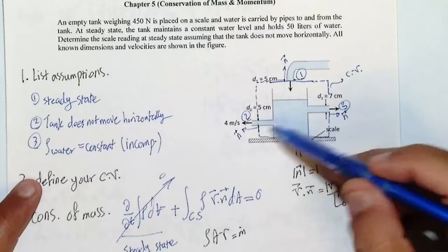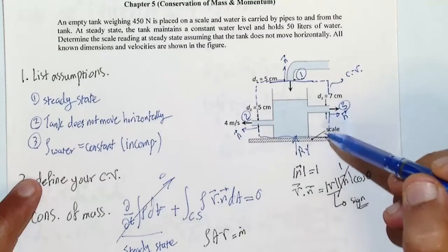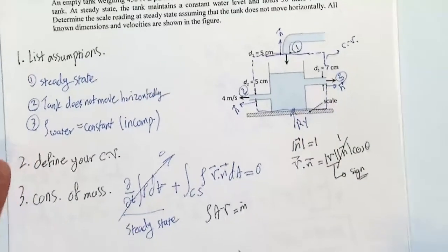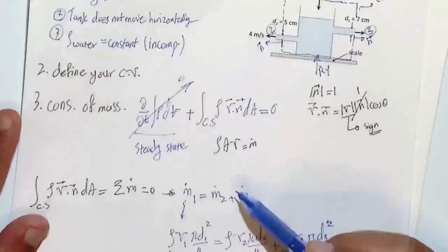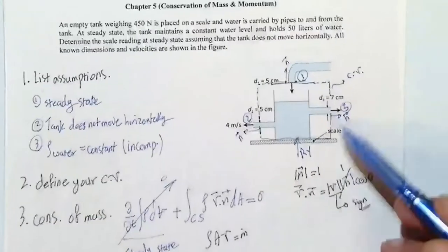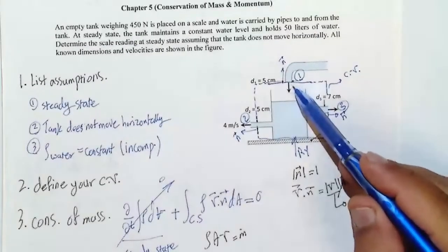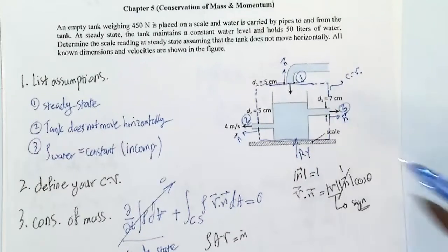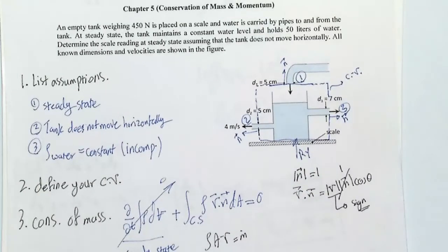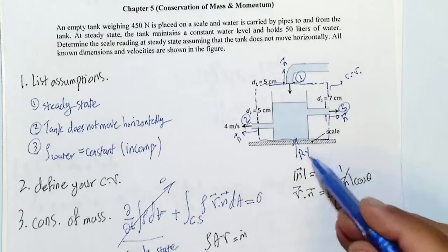By using the conservation of momentum in x direction, you have one equation, and using conservation of mass, you have another equation. Using these two, you can find V1, and then you can apply conservation of momentum in y direction and find Ry. That's the whole story. I just summarized it again to make sure you follow me till the end, because it was a long question.